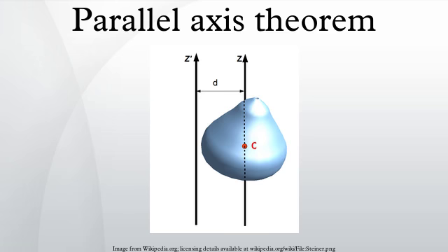Polar moment of inertia for planar dynamics. The mass properties of a rigid body that is constrained to move parallel to a plane are defined by its center of mass R = (x, y) in this plane, and its polar moment of inertia I_R around an axis through R that is perpendicular to the plane. The parallel axis theorem provides a convenient relationship between the moment of inertia I_S around an arbitrary point S and the moment of inertia I_R about the center of mass R.